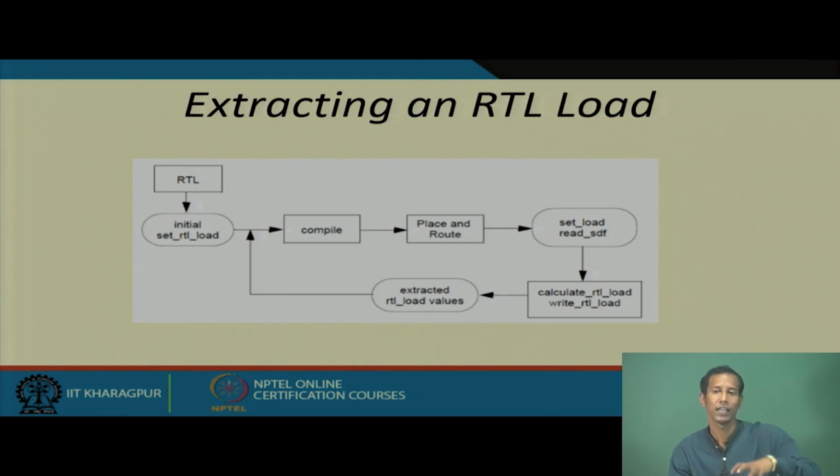So, all the C and R values you have to extract, and then again they will be back annotated and calculated depending on whatever RTL code you have written. So, it checks the timing. Suppose you have set the timing, okay, my clock period requirement is let us say 5 nanoseconds. It performs all these steps, and then again all the delay information is calculated, and it corresponds to your required time. If you have said 5 nanoseconds, that is your required time.